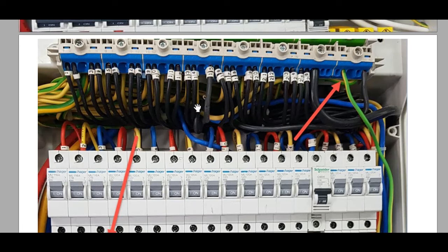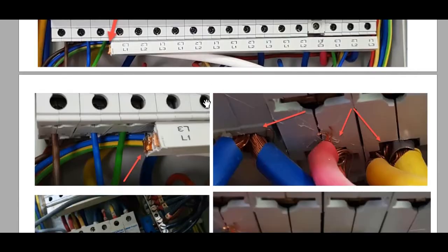As you see here, also this wire has some damage. Why? Because sometimes during use of the screwdriver or something like this, it makes a weak spot on this wire, so care must be taken. At least we must put tape in this area, so you can check for this one.